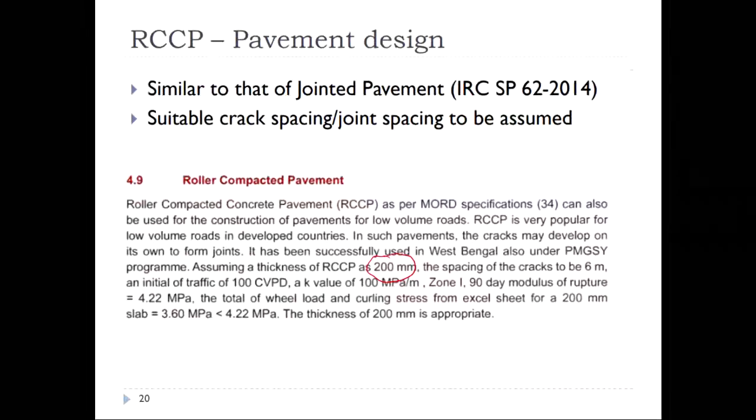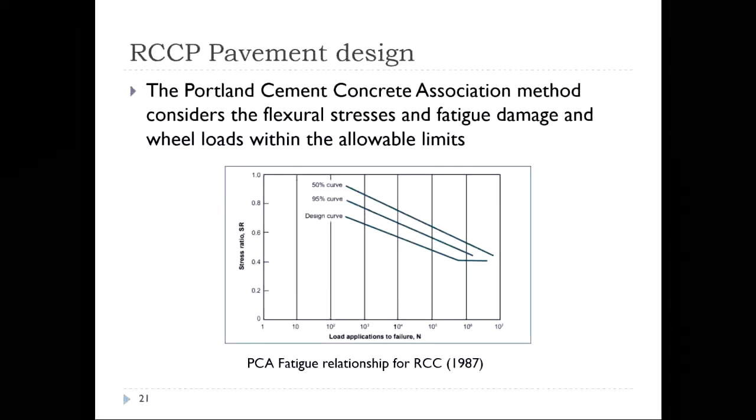So this is the design procedure suggested by IRC SP 62. But there are other established design protocols given by the Portland Cement Association, the PCA method.